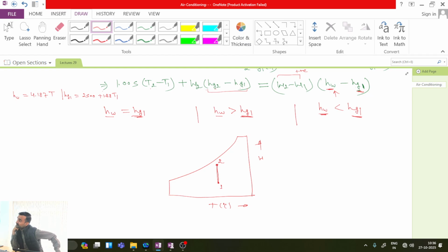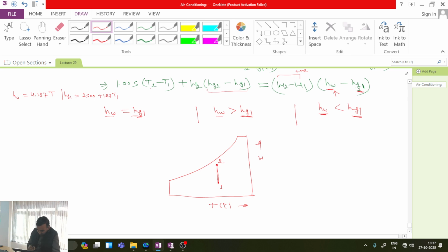Okay, we are adding steam. So when we will be adding steam, though we will be able to achieve humidification, but along with the humidification process now, temperature will also increase. So I will be getting process 1 to 2. Now humidification is also taking place. However, temperature is also changing from 1 to 2. Is this point clear? Clear or not?